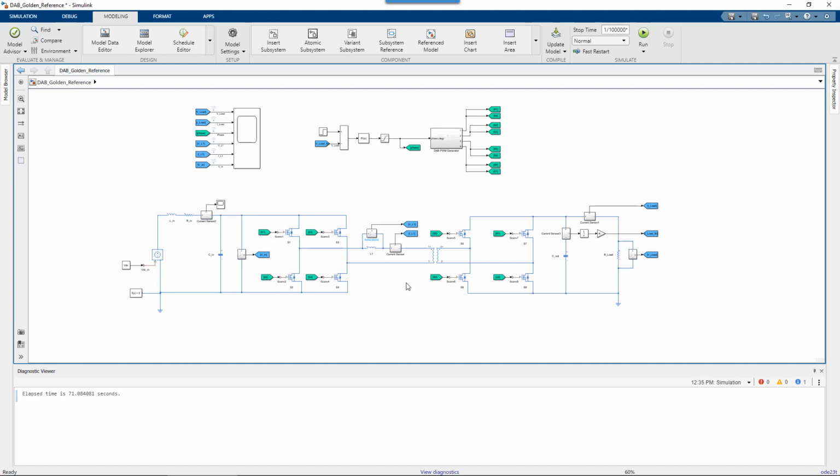What are some of the details of what variable step solvers do behind the scenes? Like a difference between ODE23T and ODE15S is ODE23T is tracking its maximum potential numerical error, and the other isn't. What does that even mean? I didn't explain enough. Some of you might know what that means, but some of you might just be like, what in the world are you talking about? I can get into concepts like that in a separate video, but this video is much more just how can you go about this? What can you do?